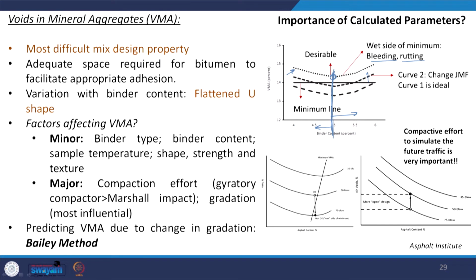But as I just explained, if it is on the wet side, it can be prone to bleeding and rutting. So, understanding this variation for a particular mix design problem is very important. Now, if you see the various factors that are affecting VMA,